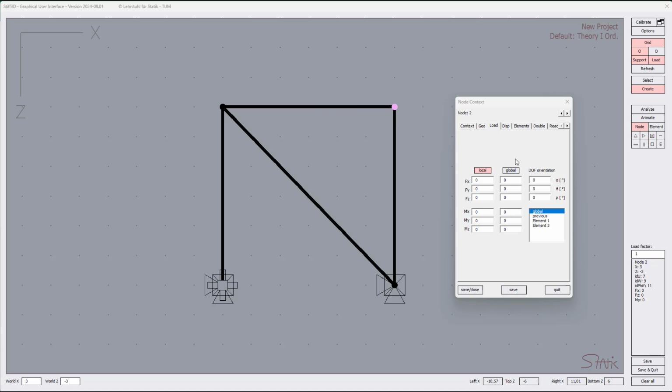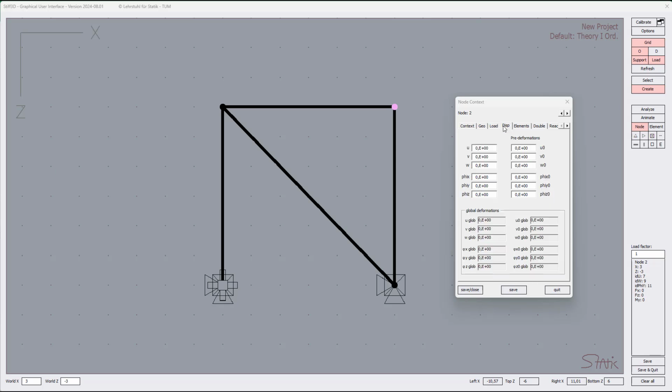Everything fine. And let's proceed here with our table. So that's the top disp. Here we recover the displacement components after analysis. The displacement components u, v, and w are aligned to x, y, and z, either globally, like now, or in the local directions.